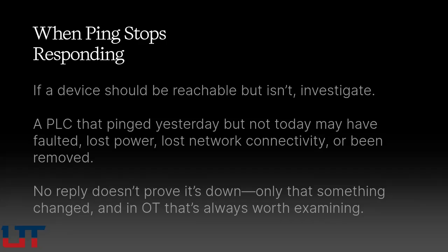A PLC that responded to ping yesterday and doesn't today may have faulted, lost power, lost network connectivity, or been physically removed from the network. The absence of a response is a signal that something changed, and changed things in OT environments are always worth examining.